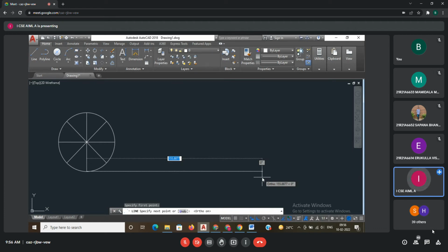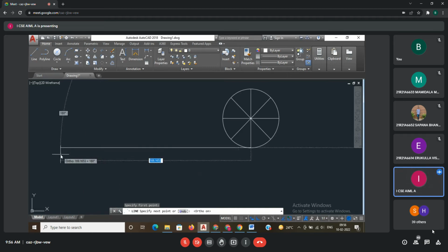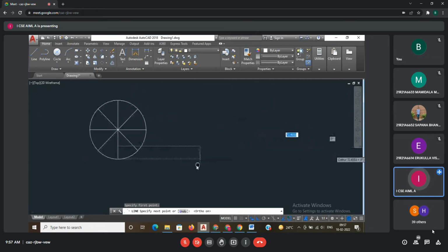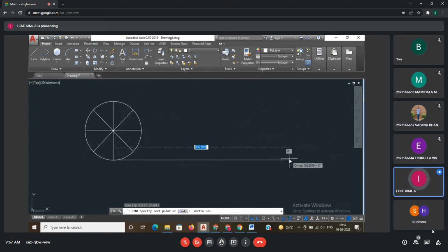But why are you drawing in a right side direction? Why can't you draw in a left side direction? You can draw here also. Your cycloid will be in the opposite direction. That's it. You can draw here also, then the circle rolls in an anti-clockwise direction. Here it is clockwise direction. That's why I want to draw one horizontal line.